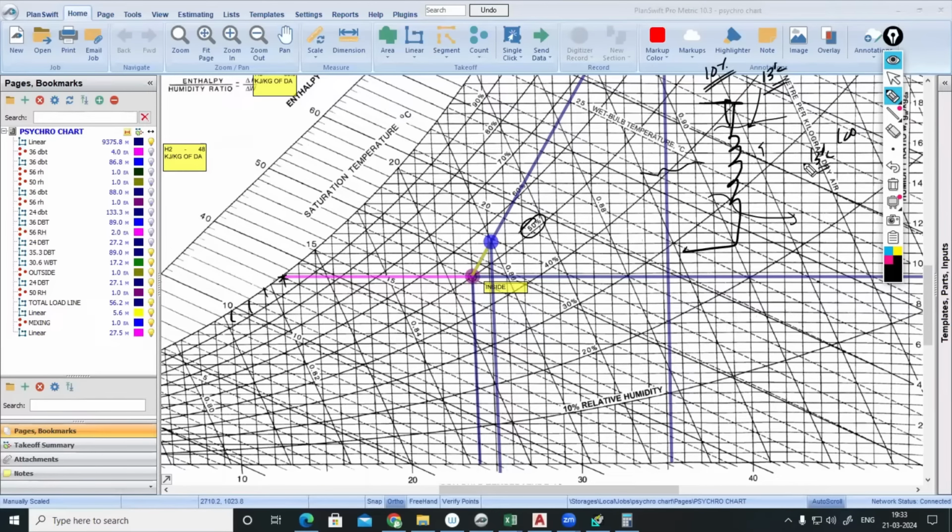But that's why, 90% of 2600, let's say 90% of the air will be leaving the cooling coil at 13 degrees Celsius. The remaining 10% of air will not achieve this 13 degrees Celsius. So effectively, by the effect of this 10%, when the air is leaving the cooling coil, the temperature will not be 13 degrees Celsius. It might be higher than that. So when we are considering the bypass factor, again, the dew point temperature has to be decreased.